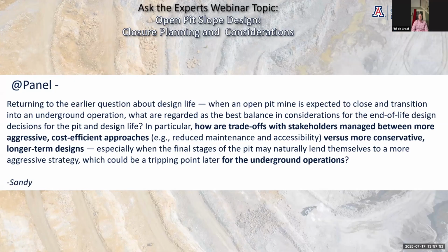The one part of the question was about trade-off studies with a bigger exclusion zone or a smaller exclusion zone, depending on, I suppose, the aggressiveness of the underground or the open pit mine in late stage mining. I think the trap that many of us engineers fall into is to just boil it down to a straight economic outcome and a factor of safety. Tia was highlighting that factors of safety are not a particularly good mechanism for communicating with stakeholders. They want to know about performance and